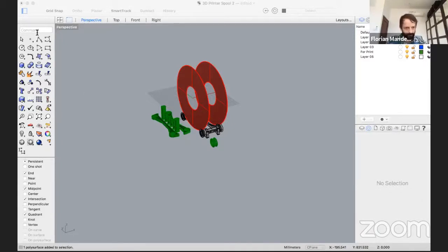To create something, that's on your left side. So that's the panel with your toolbox, basically. The easiest is you start with a polyline. And actually, I'm always using polylines. I never use points or anything. Polyline means you define a coordinate in space, and I usually start with 0, 0, 0.